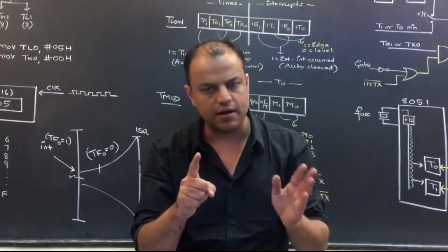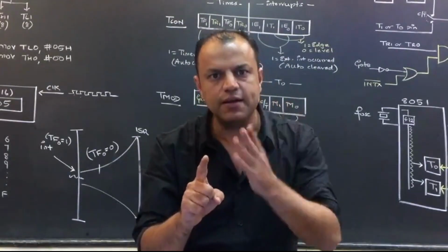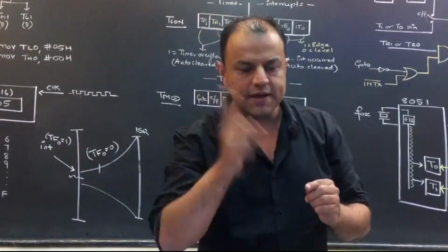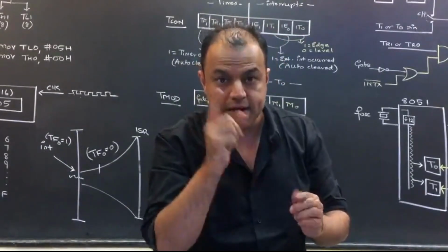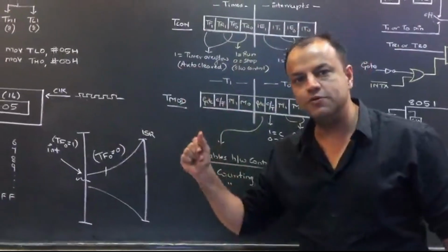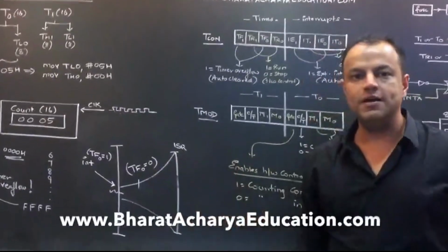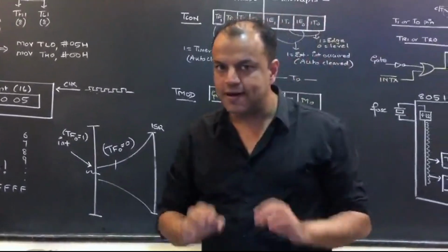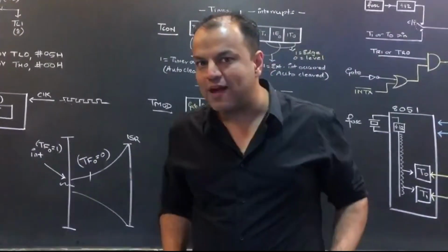the ISR right now. That doesn't mean the processor will forget that this interrupt has occurred. This flag will keep reminding the processor, I am pending, I am pending. Whenever the processor finally goes to the ISR, this information is no longer required and the flag automatically becomes 0. Please tell me, did you understand? Is the role of timer overflow flags clear?